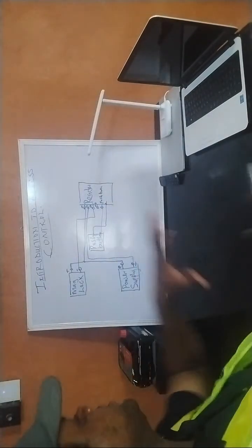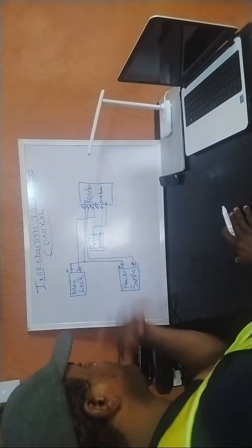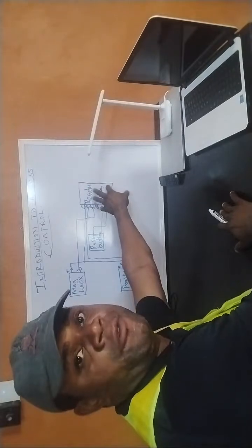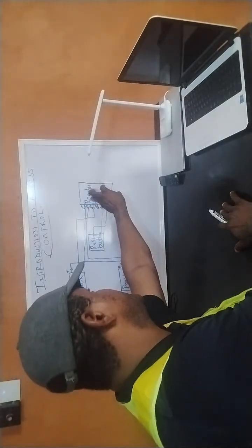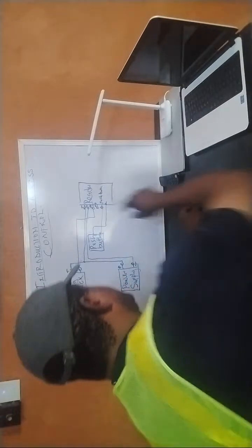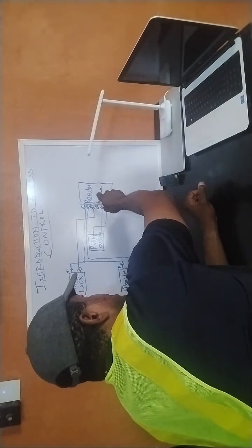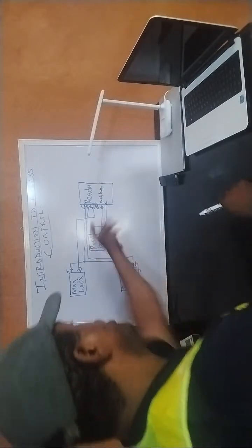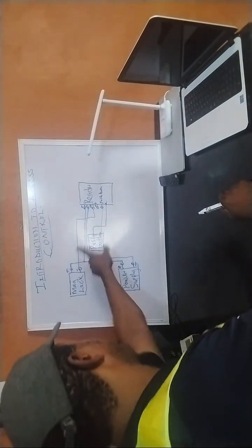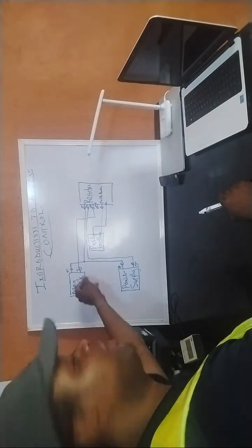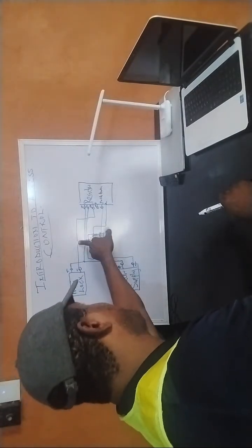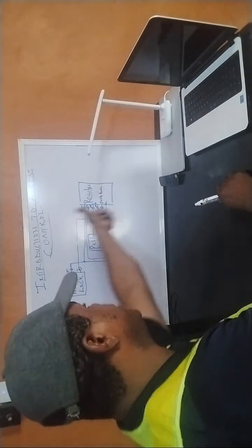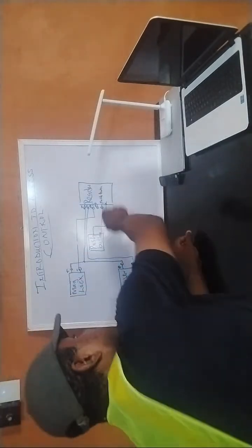So how does this system operate? Now, I think the whole configuration is fine. By the time you puncture any of the keys here, this normally closed contact will switch from a normally closed contact to a normally open contact. It means power supply to this magnetic lock is cut off within that time. If a correct password or the right biometric comes into this, it will change.